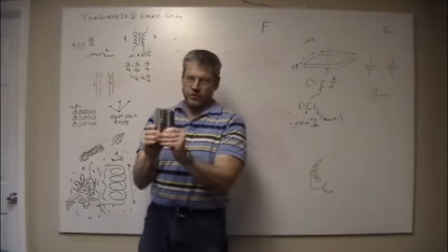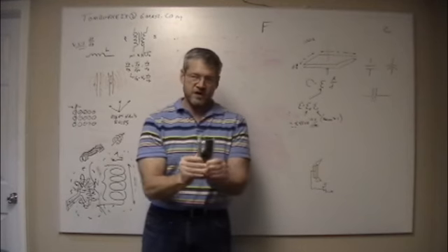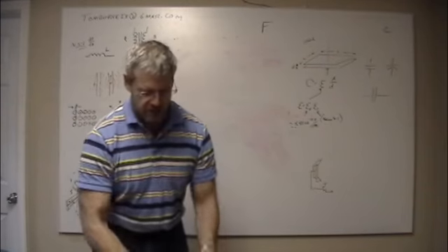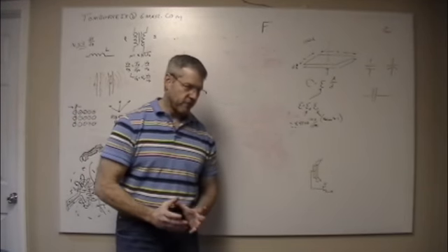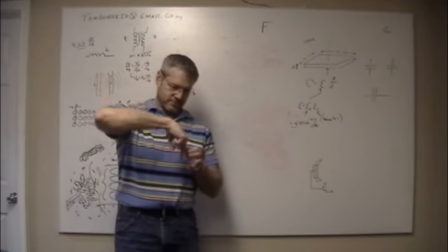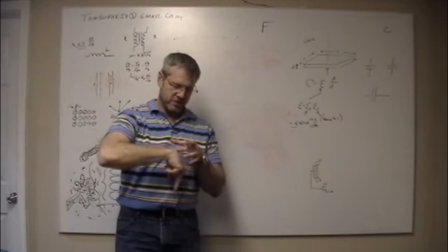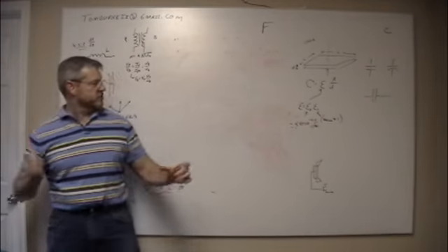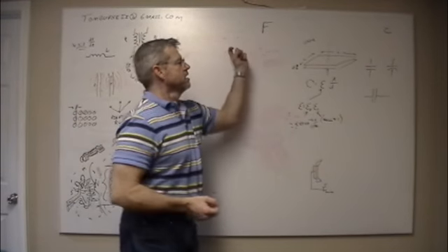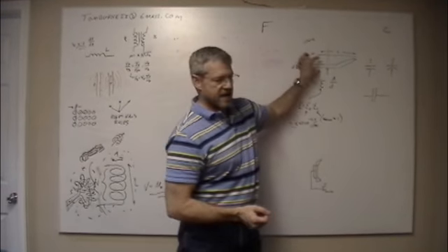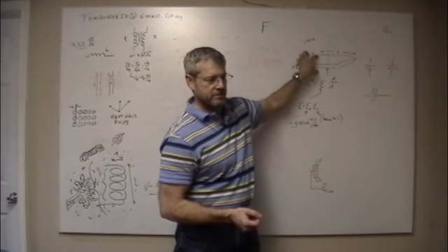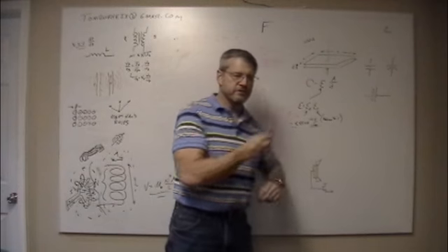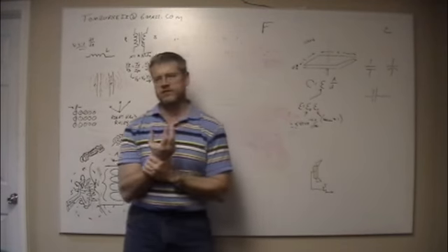If you look at the old days when they were first learning about this, Ben Franklin and whatnot, Leyden jars, it's a capacitor. It's a glass jar that's lined with foil, and it has a probe that comes down the middle, and it's all isolated. What you're doing is pulling electrons away from that metal, and that's creating an electrostatic field in between the 2. So there's fewer electrons on this side than there are on that side. It's creating an electric field, and that electric field is storing the energy.